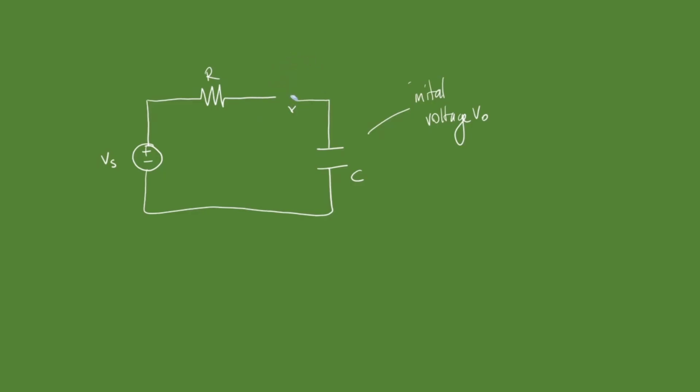But to avoid having to draw switches and directions and everything over time, we say our voltage source has a certain voltage, Vs. That's the same thing we had before, but this time it's going to be Vs multiplied by U of t. All right, this is a little foreign. I'm going to explain what this is. U of t is what we call the unit step function.